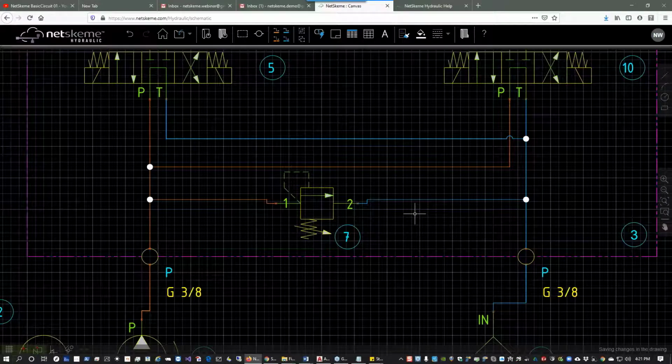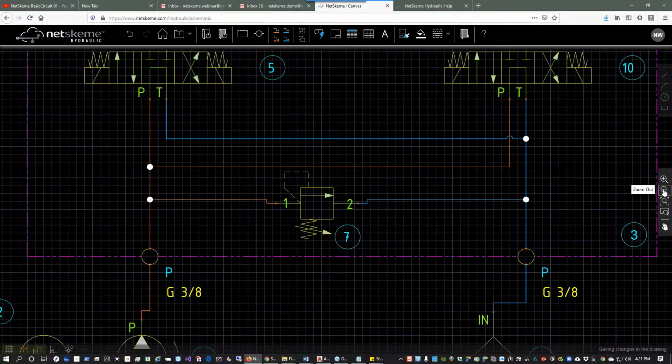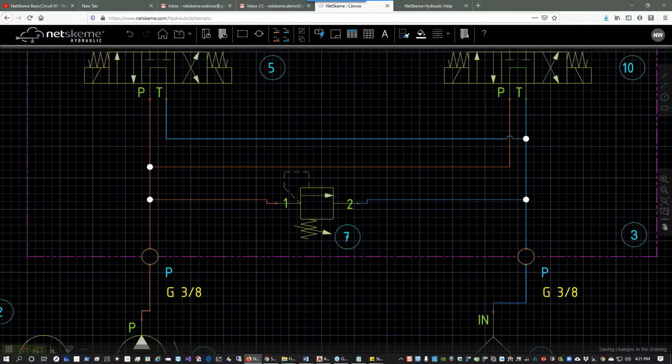There are other drawing settings that are similar to those found in other popular CAD applications. We'll not cover these today due to time. The drawing object bar also has some features related to the viewport. Clicking the zoom in icon expands the viewport based on its center point. Conversely, clicking the zoom out icon contracts the viewport. Note that zoom functionality can also be achieved using the mouse scroll wheel, but instead acts on where the cursor is positioned within the viewport.